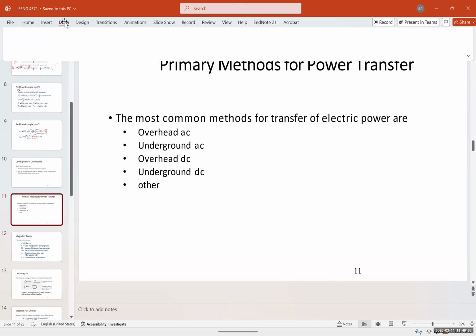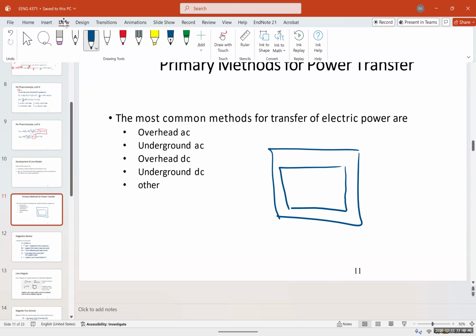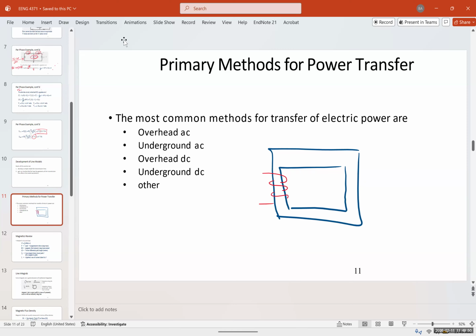Let me give you an example of a transformer. This was actually an interesting question from the FE. If we have a transformer, are you already familiar with transformers? Okay. Imagine this is connected to 200 volts. N1 is 10. N2 is 1000. What is V out going to be? 20,000? We think it's 20,000.